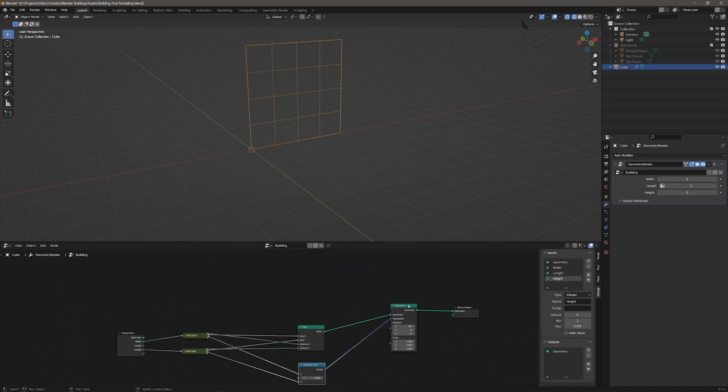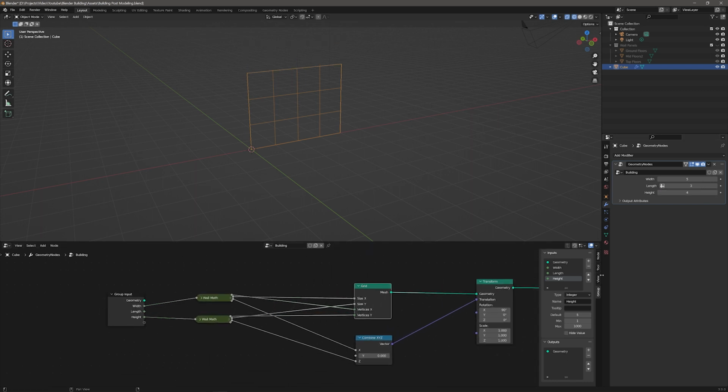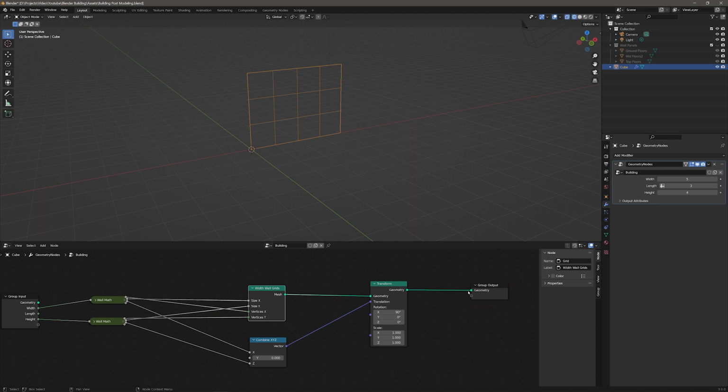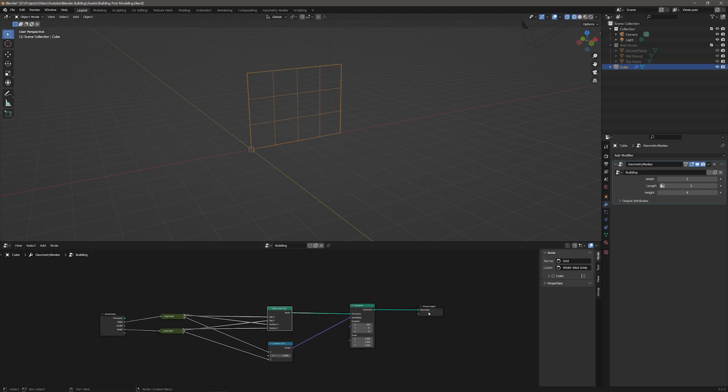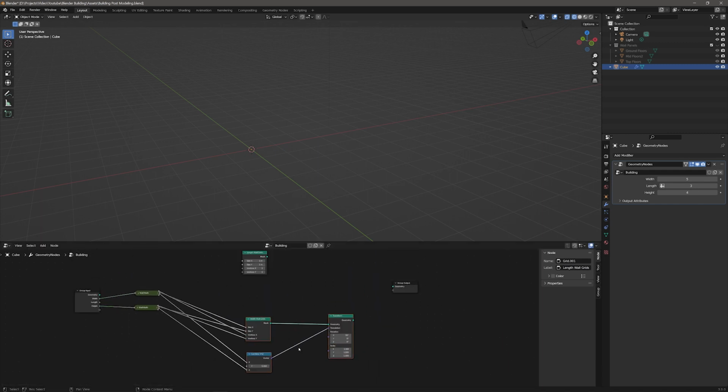So now that I have the basic wall, I'm going to call this grid my width wall, because I actually need this grid twice, once for the front of the building and once for the back. I'm going to end up using this same grid twice after doing an additional transform at another time. But for right now, I want them both in the same place. I also need a second set of grids that are going to do the left and right side of the building. So I'll create my length wall grids,